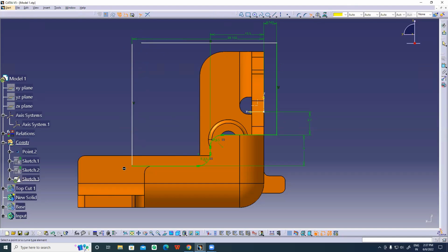So I'll just go to a trim. This line is not connected. I will be connecting this, and I will be going to a dimension. Let me apply a dimension to this trim. And I don't know why this is under constraint. We'll try to move it.